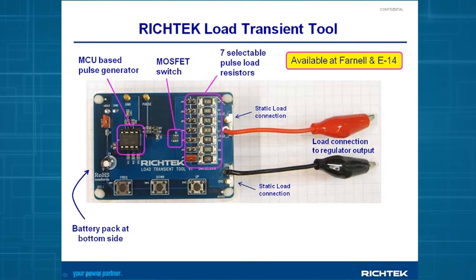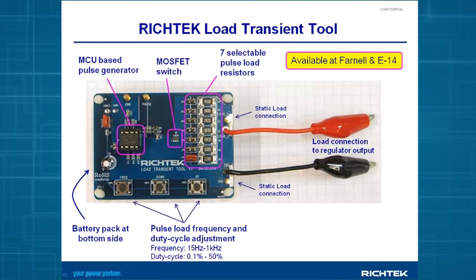There is underneath the board a battery pack, so this tool is completely portable and completely isolated, which means you can use it at any part of your application without having issues like ground loops or other problems. 3 buttons on this board will control the frequency and the duty cycle over a very wide range. So this board can be used to test almost any converter, from buck converters to boost converters to linear regulators. You can even measure LED drivers with this tool.